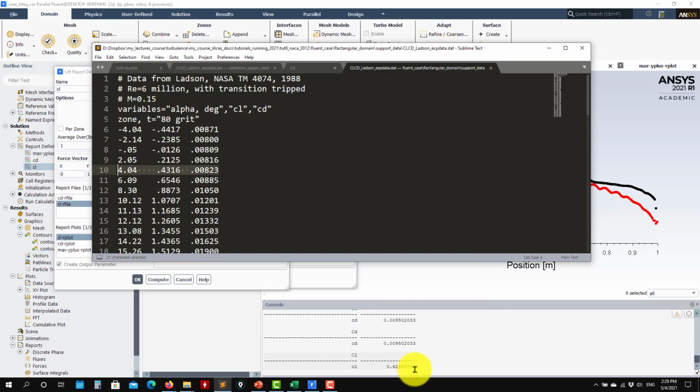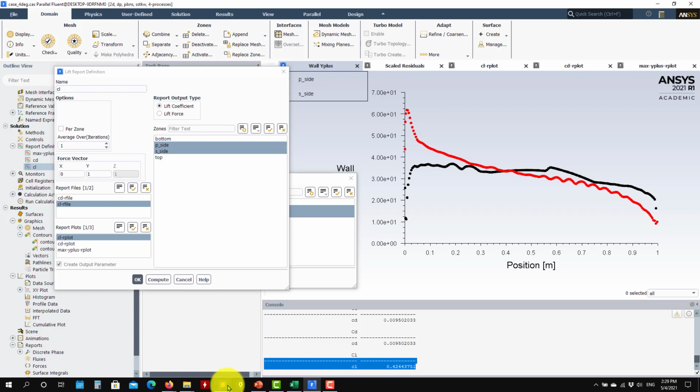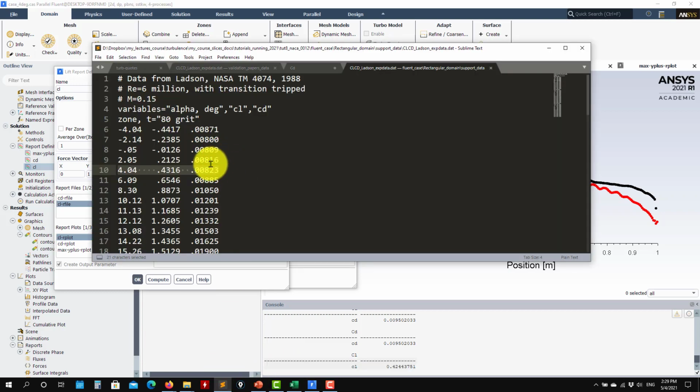See that for the lift coefficient, you have a very good agreement, and usually getting the agreement with drag coefficients is the difficult one. So see that there is some difference there, but it is around the ballpark. We're following the trends, but this is the most difficult one. And here, in this case, we're using wall functions, and wall functions tend to be very accurate. There are some situations that it would give you some differences.